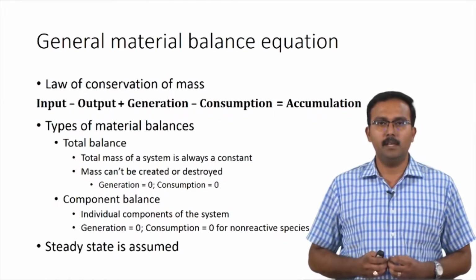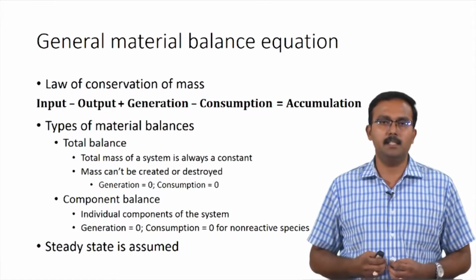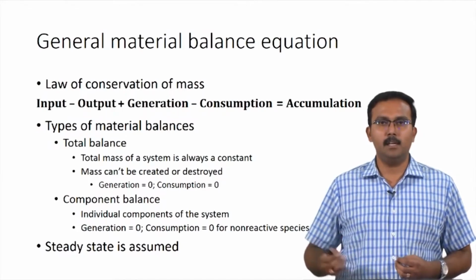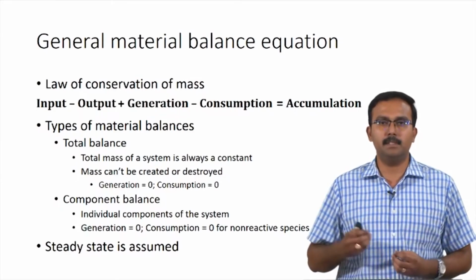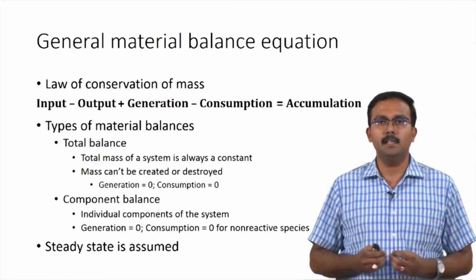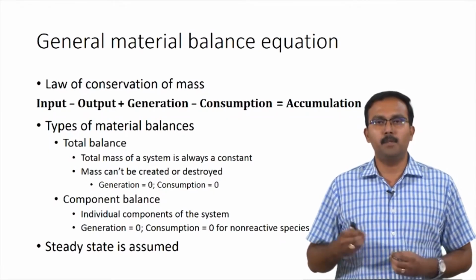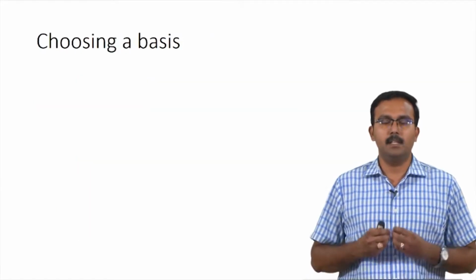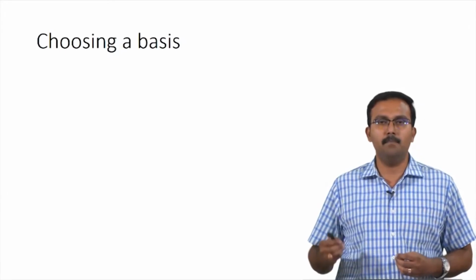In most of our calculations we have been assuming steady state. As I had already justified in the earlier lectures, most chemical and biochemical processes and industrial processes operate under steady state conditions except for states where it is either a startup or shutdown of the process. For this reason, assuming steady state is a reasonable assumption and we can proceed with performing calculations by ignoring the accumulation term.